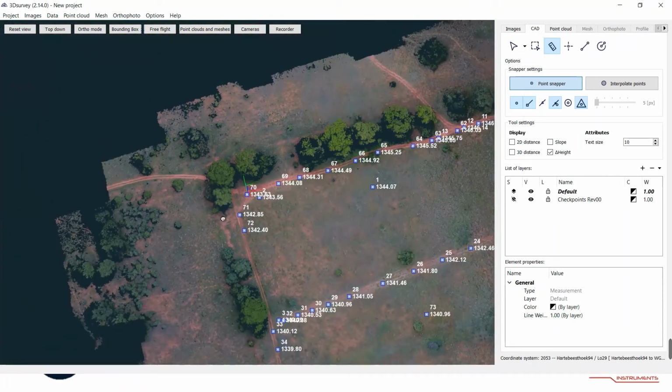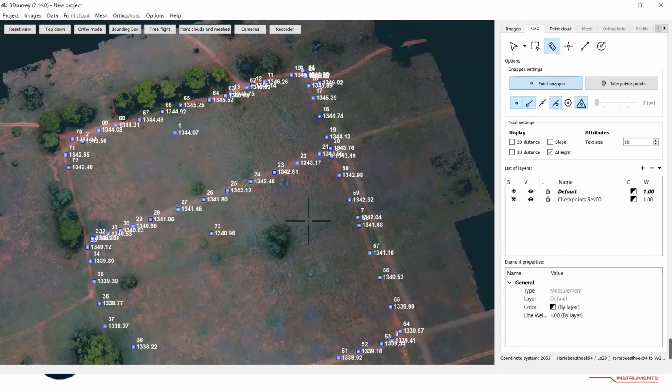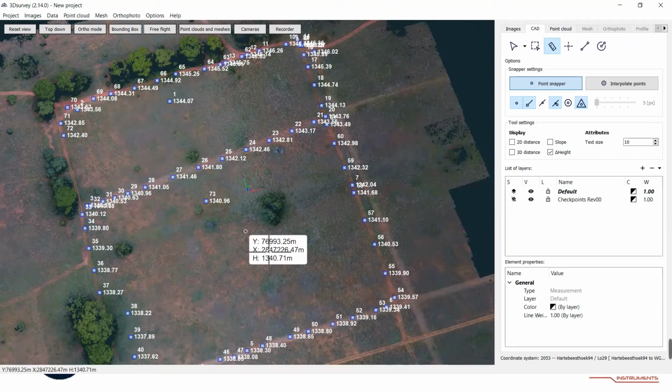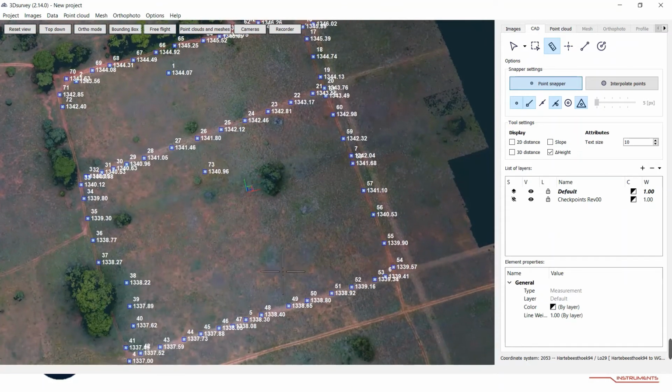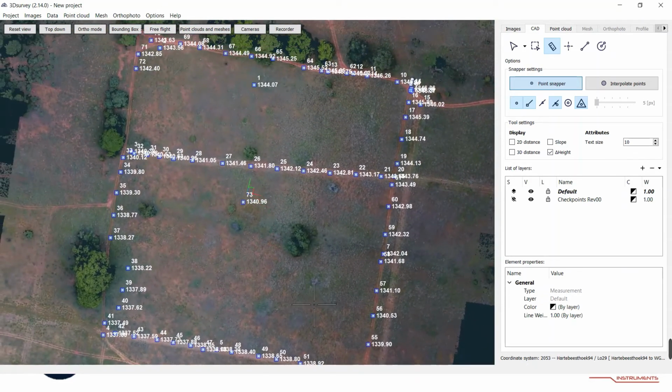I can definitely say, and this is all GPS data that was accumulated here. So remember that your GPS also pushes into the ground. So you'll always have a bit more than, it's a 2 centimeters or 3 centimeters difference from your GPS data to your actual point cloud. But just to get it this close means that your survey is actually good and you can really use it for whatever you need to.